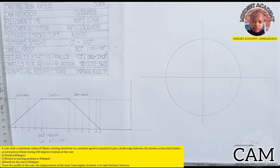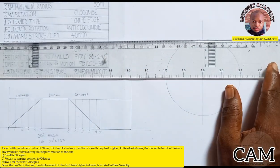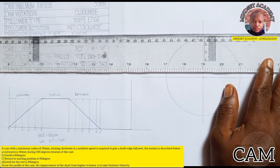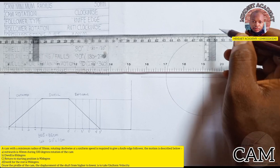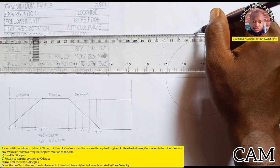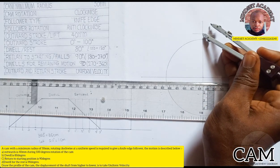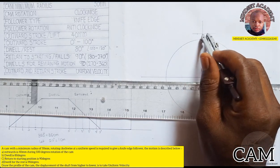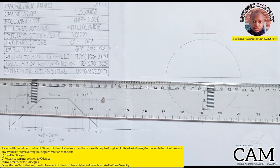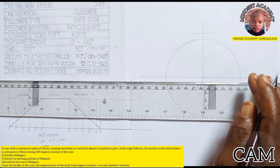So what I'll just do is, I'll just construct a cam here. I'll place it at this point here. Just draw a horizontal line this way. Then you can just pick two different points, this point and this point. So it's not offset. It's just having the same center as that of the cam.